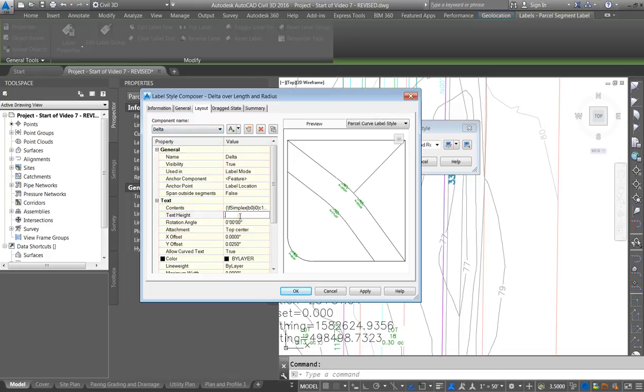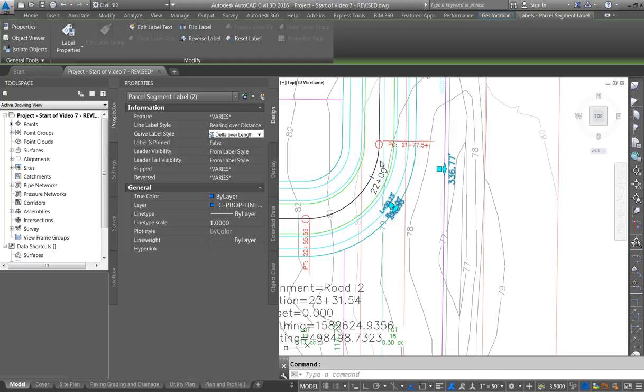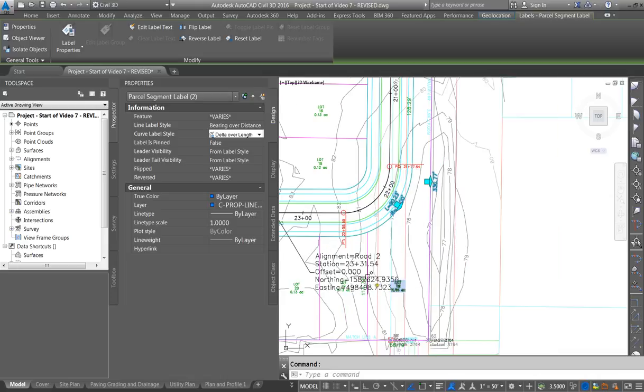I'm going to go ahead and change that to 0.075, and I can just turn the visibility true and false as I go back and forth. At the end of the drawing, when we go to turn it in, we'll have to turn those back on. So apply and OK. But for right now, for cleaning this up so I can see when I'm looking at distances, I don't want a lot of clutter.